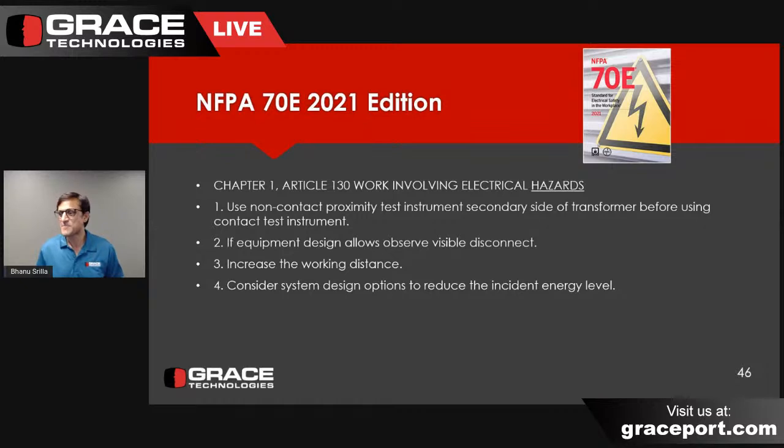And risk assessment: if you do a risk assessment for a job, a discrete work task where the worker is exposed to arc flash, you can use up to a 140 calorie per centimeter squared arc thermal performance value arc flash suit, completely valid. An 8.7 calorie coverall provides the same arc thermal performance value as a 140 cal arc flash suit, which is a 50% probability of the onset of a second-degree burn injury. The blast pressure might be higher at 8 calories or higher at 140. There are other factors, which are coming up on the slide.